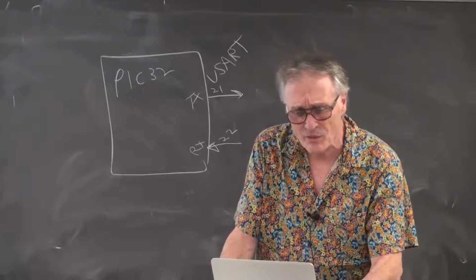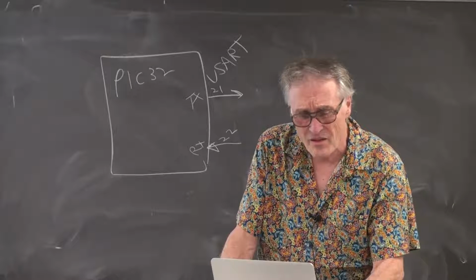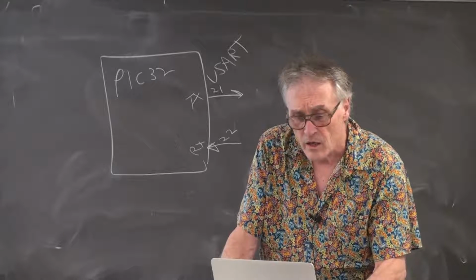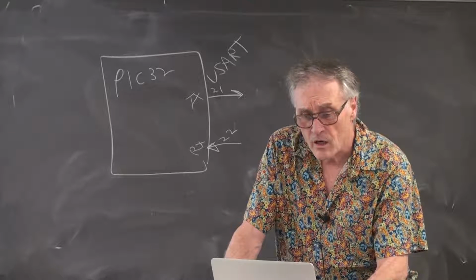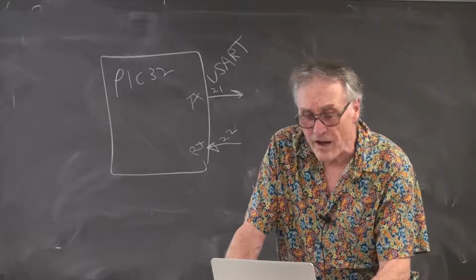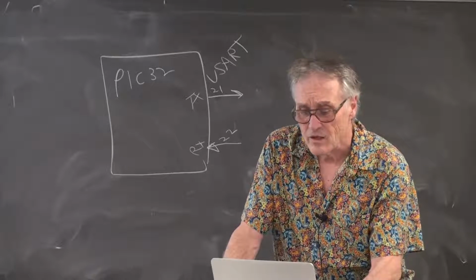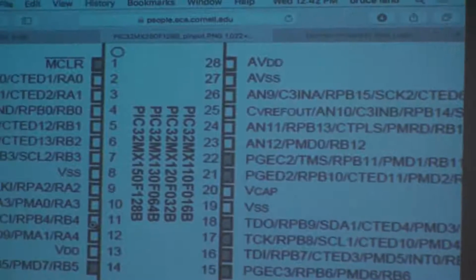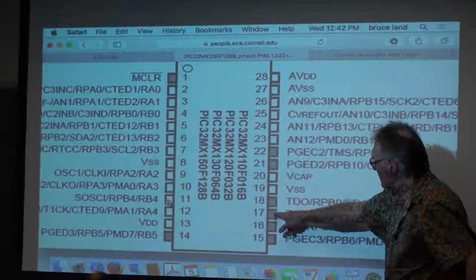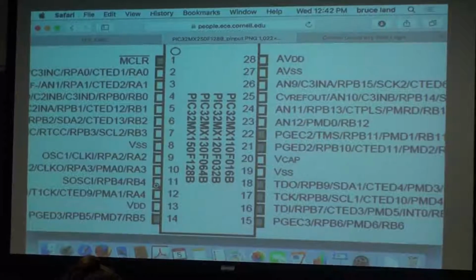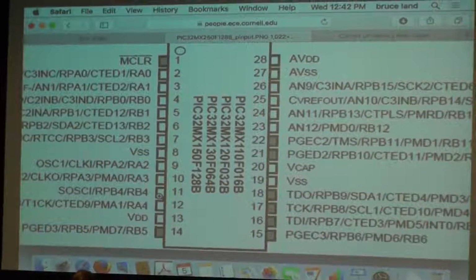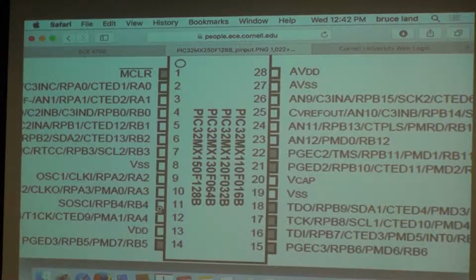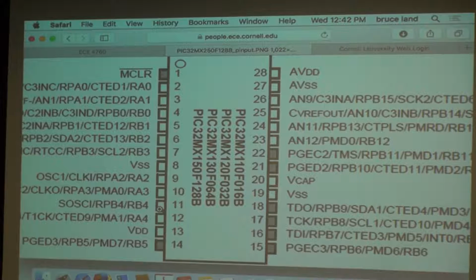And the way they're special is that they are 5-volt tolerant. So if you look at this diagram of the pinout of the chip, you'll see a few of these pins are grayed out here. The reason they're grayed out is to indicate that they can tolerate a 5-volt input for a 3-volt system and not blow up. So in particular, pins 21 and 22 are 5-volt tolerant.